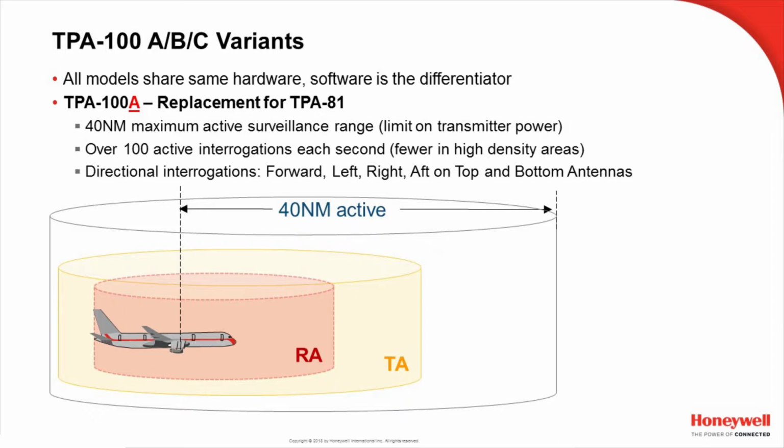Now, just to stop here for a minute, also point out that in the surveillance volume we have a 40 nautical mile range. TCAS is also looking 10,000 feet above and 10,000 feet below the aircraft. The display, the part that the pilots look at, there's a control switch so they can select, and most control panels have this, your specific installation may not, but many have an above-below normal switch. So in normal position, we're only displaying aircraft that are 2,700 feet above and below, but if we select above position, now we're going to put on the traffic display aircraft up to 8,700 feet above. And likewise, in the below position, we're going to display aircraft all the way down to 8,700 feet below.